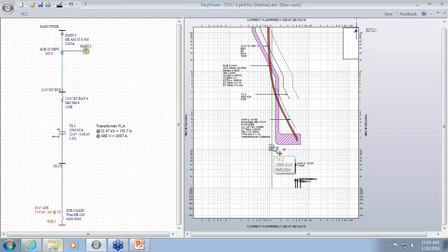So I like to add a little bit of safety on the maintenance mode setting. And so the best in this system, as far as a fault with the relay protecting it in the maintenance mode, is 11.8. So with the time delay, it was 19.8 calories per centimeter squared. So, depending on at what PPE level you change over, if, say, you only went up to 8 calories, you may not care to enable a maintenance mode setting in this case.